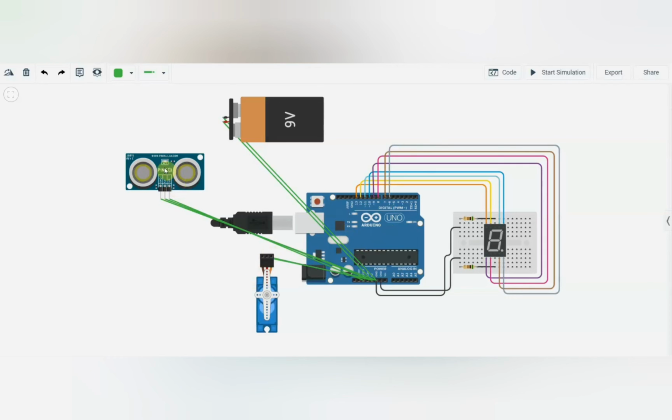And this is an ultrasonic distance sensor, which is used in measuring the level of water in the tube, which indirectly measures the amount of air in the tire. This battery supply is just given as 9 volt for an example. Actual battery supply could be taken from the battery of the two-wheeler itself, which doesn't add any additional cost.